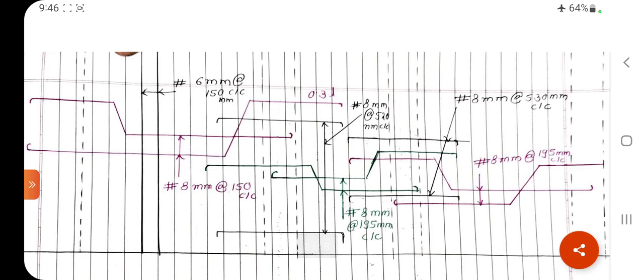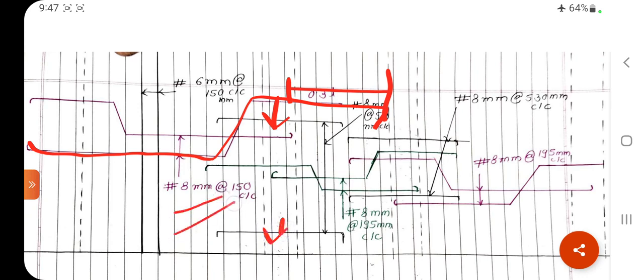Now the last part of the slab is nothing but the reinforcement detailing. Here how the reinforcement detailing is done, look over here. Here the first span steel coming from the support is bent up over here. This extension is of 0.3 L. Similarly here the extra top steel. Okay, here the spacing is 150 mm. This extra top steel is provided at the support.